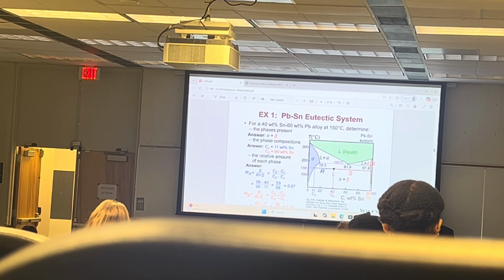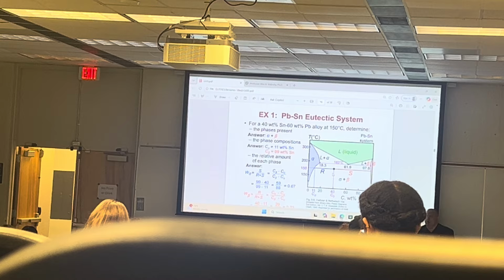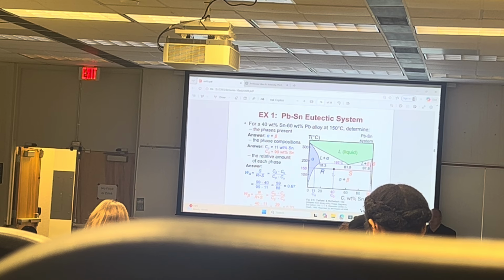And this guy brings me a wafer that has gold on silicon. They said we annealed it at 400 degrees C, and I stick it in the microscope and I see liquid drops. So silicon and gold form a eutectic, and they annealed it, and there was something about the process which is irrelevant, what was wrong with the process. The bottom line is that gold deposited on silicon melted the silicon, and they were like raindrops on your car windshield. That's what I saw.